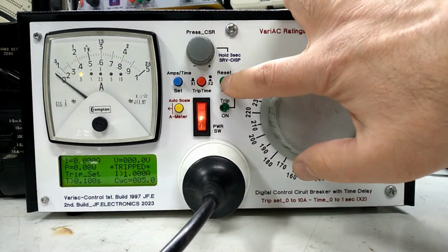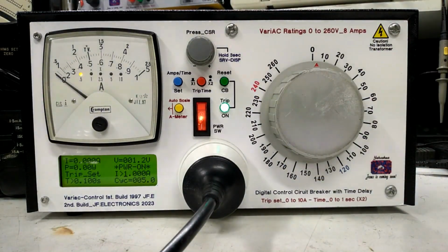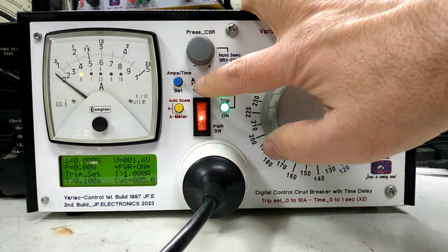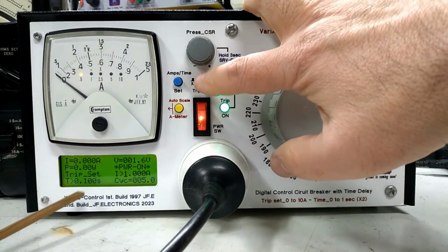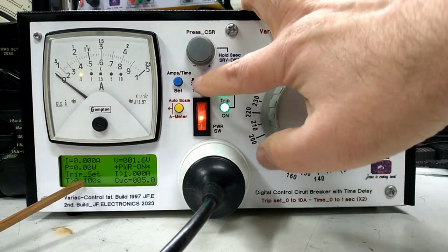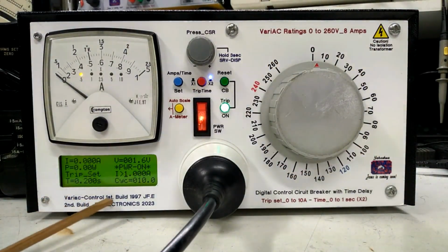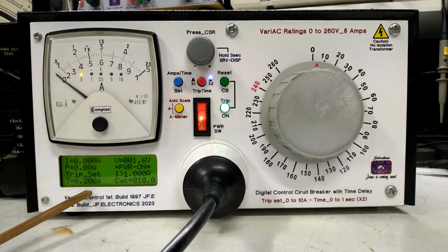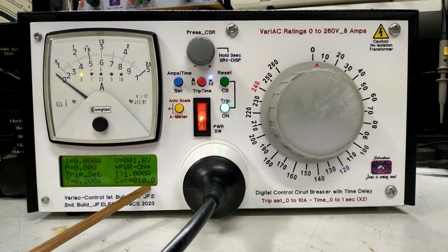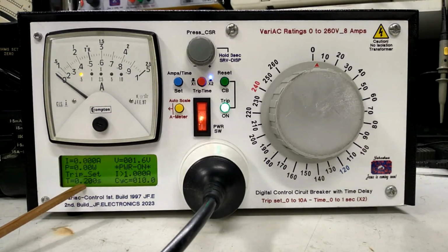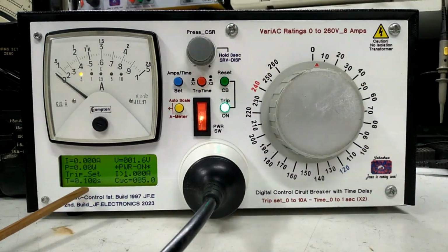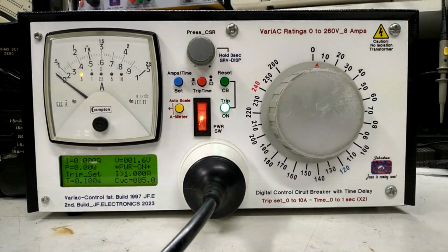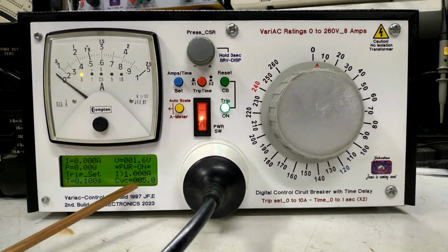reset button. So you press that to reset it. We have the ×2 for the time delay. So at the moment it's 100 milliseconds, and when you press the ×2 it will change to 200, so it doubles it, and it shows the cycles, so the cycles for the 200 milliseconds. So go back to 100 and it's 5 cycles, because it's the formulas worked out under 50 Hertz.